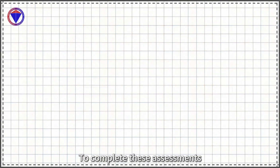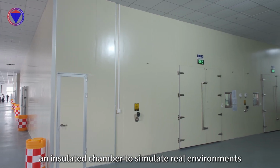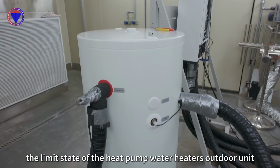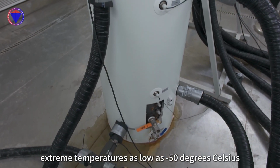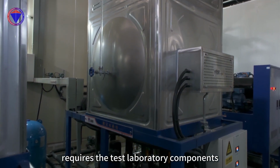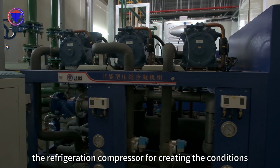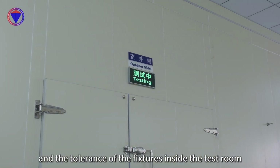To complete these assessments, verifications, and calculations, engineers have designed an insulated chamber to simulate real environments. This environment sometimes also needs to test the limit state of the heat pump water heater's outdoor unit, which might require extreme temperatures as low as -50 degrees Celsius. Such extreme temperatures require the test laboratory components to be designed to a high level, specifically in the performance of the refrigeration compressor for creating the conditions, the insulation of the chamber structure, and the tolerance of the fixtures inside the test room.